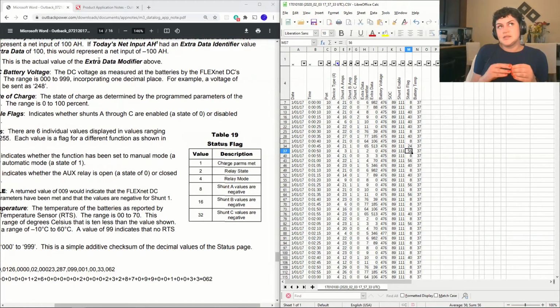Because technically, depending on what the status is, if, for example, you're charging from PV and the grid, you might have the opposite. Let's see. No, it would both be positive, because positive is going into the batteries and negative is leaving the battery. So from the PV to the batteries is always going to be positive. And between the battery and the inverter, it could be positive if you're charging, and it would be negative when you're pulling.